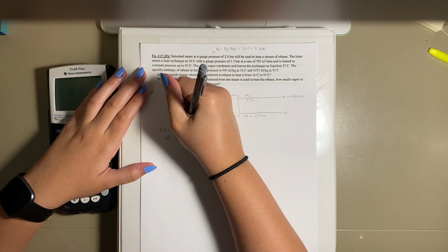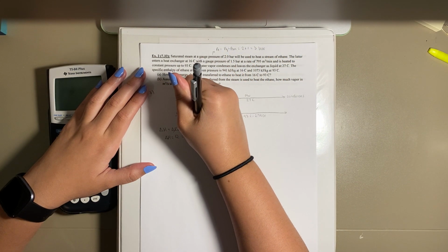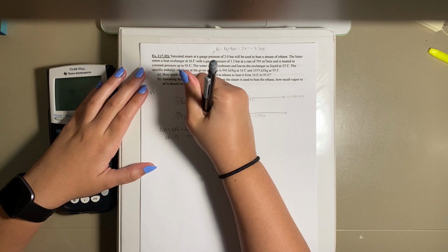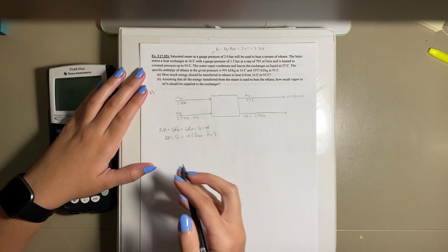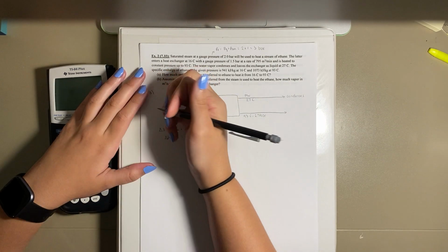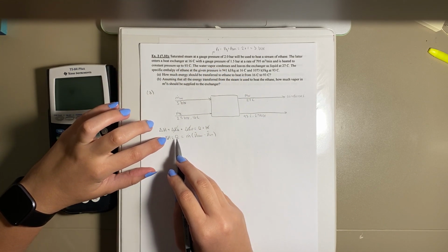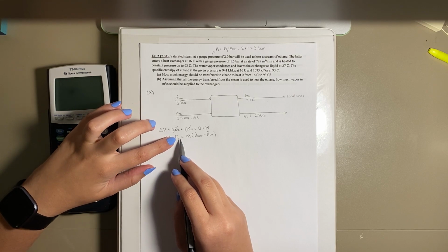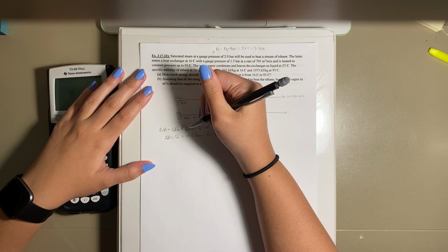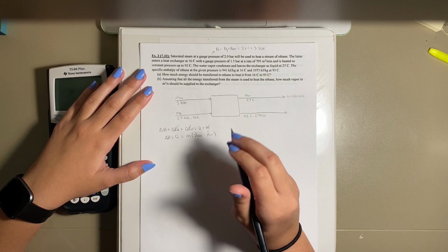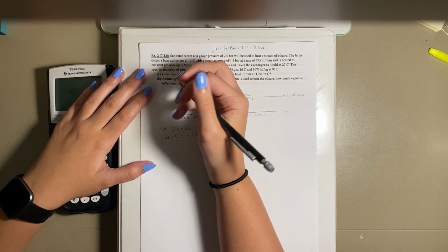And that is going to equal the mass flow rate of the ethane times the specific enthalpy out minus the specific enthalpy in. So we can calculate the delta H, which is going to equal the heat that we're looking for here. But what we need is our mass flow rate. So we're given the volumetric flow rate. We just need to solve for the mass flow rate using ideal gas law.